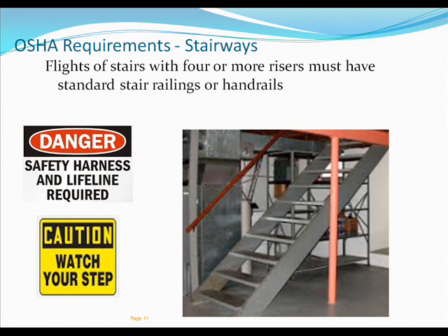Stairways having 4 or more risers and more than 44 inches wide but less than 88 inches wide must have one handrail on each enclosed side and one stair railing on each open side.